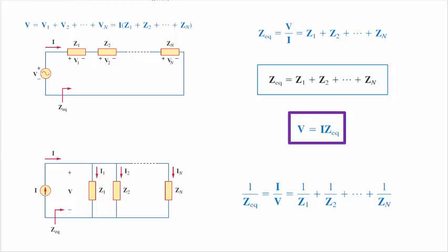So you're going to go through every single circuit element and write down what its impedance is. If it's a resistor, you'll write down its ohms. If it's a capacitor, you're going to write down 1 over j omega C for each one. This is the ohms for each one. And if it's an inductor, you're going to write j omega L down.